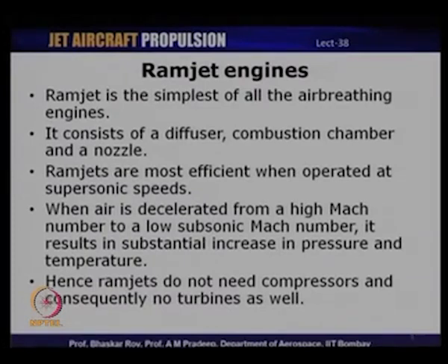So, this is probably the single most important advantage of ramjets, besides the fact that they are air breathing engines, that you do not need rotating machines, and that is a substantial advantage, both mechanical as well as aerodynamic. Well, the mechanical advantage is the fact that you do not need to carry so much weight and you do not have mechanical complexities of a rotating machine. And the other advantage, the aerodynamic advantage I would put it, is the fact that since you do not have rotating components, you can actually operate the cycle at very high temperatures, much higher than what one would use in a normal jet engine.